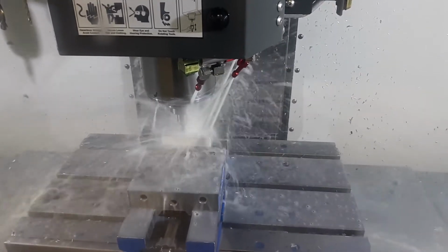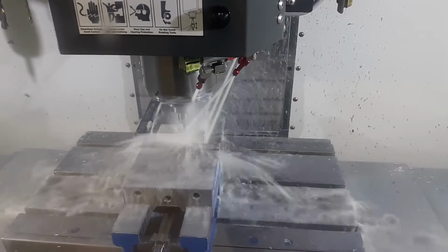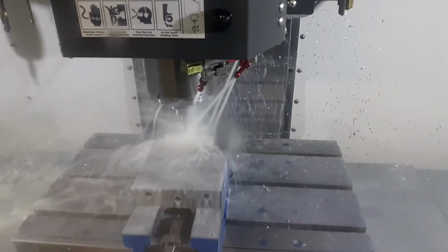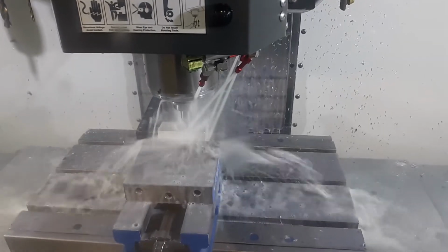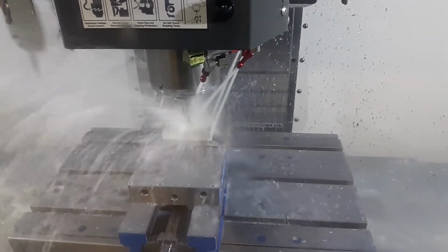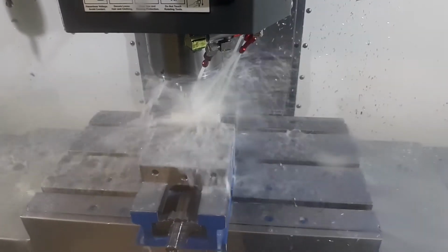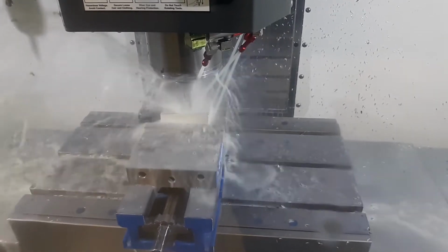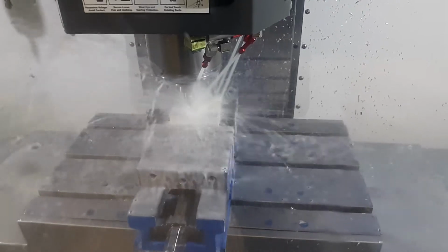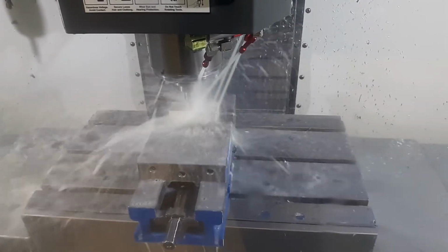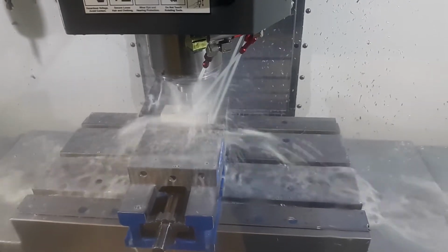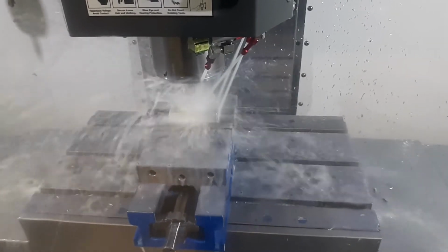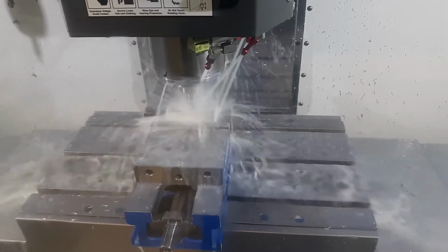Feed rate right now is 24 inches a minute. Spindle speed 4966. Last cycle was 2 minutes 12 seconds. We'll try to get this lower. Right now it's in the first increment cut, 183 thousandths deep in the part. And when it finishes that circle, it'll pop down one more level. Now it's down the second cut, 466 thousandths deep.